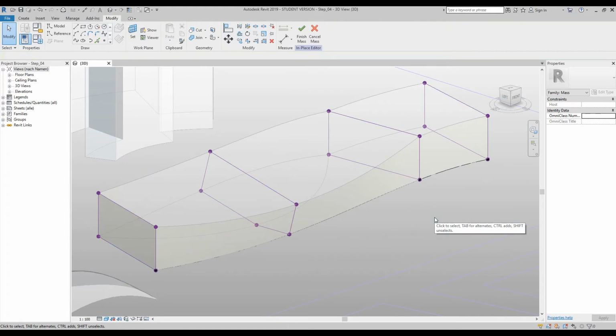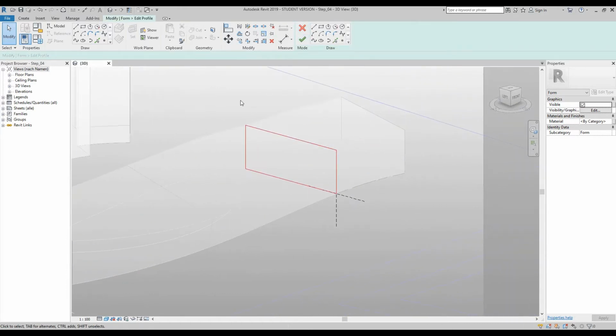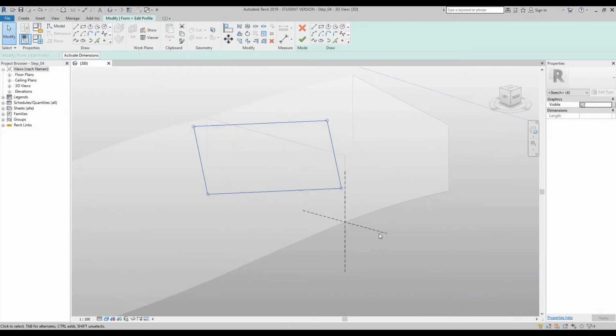So if you click in negative space, hover over this line, then tab until you find it. Again, edit profile, user interface going green, but this time we're going to rotate it from the other side. So we select all of it, go to the rotate tool, again about 1/3 in, but from the left to right, about here. Then we're going to rotate it about 15 again, so you can type 15 on your keyboard, so it looks like that. And we're going to edit the profile just a little bit by drawing a line pretty much about there. And then trim extend.